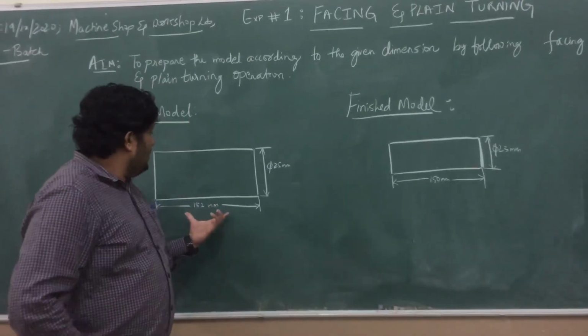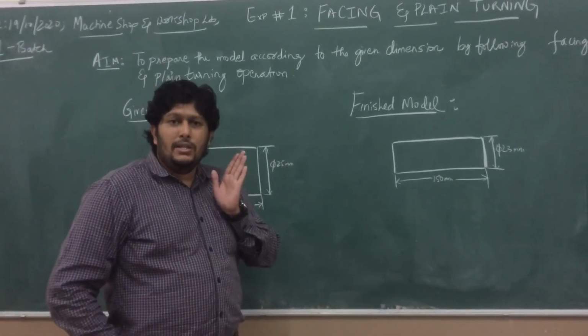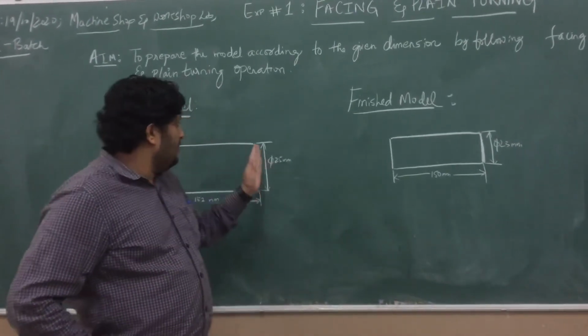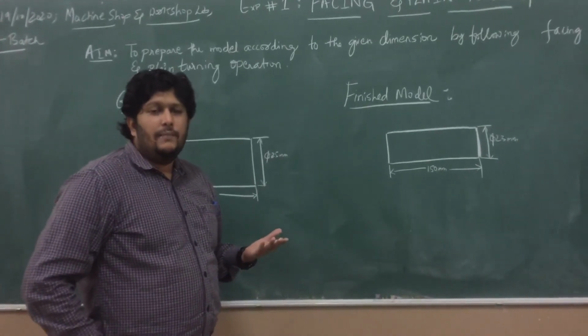Now how do we reduce the length from 152 to 150? We will introduce the tool again in a similar manner, but this time at the face. Here we can reduce the length using facing operations.